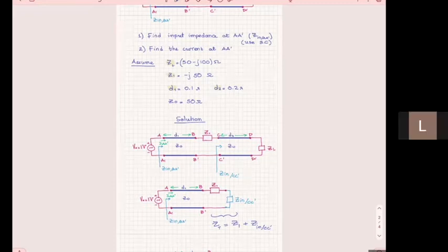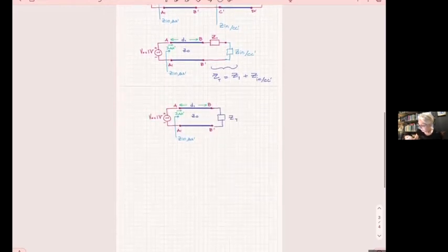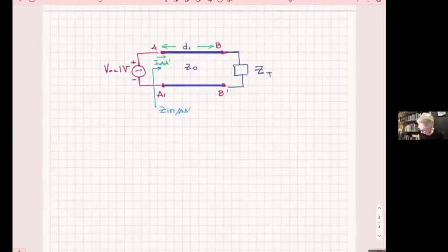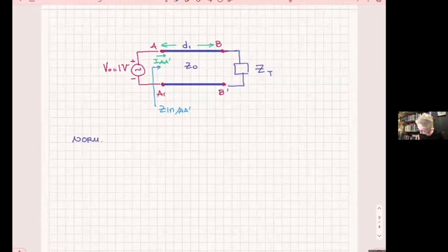You need to obtain the normalized numerical value of ZT. Excellent. I need to normalize impedances. Remember two very important things. Number one, the Smith chart needs all lengths in wavelength, but we do have those. And the Smith chart needs all impedances normalized, which we have not done yet. All right, so we need to normalize the impedance. So I'm writing here so you remember it. Normalize impedances.